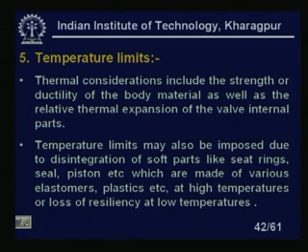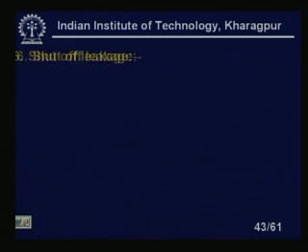Temperature limits may also be imposed due to disintegration of the soft parts like seat rings, seals, pistons, etc., which are made of various elastomers, plastics, etc., at high temperatures, or loss of resiliency at low temperatures. Okay. This is also important.